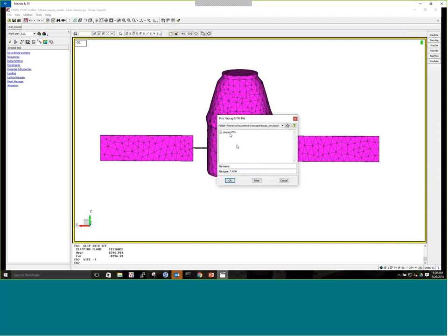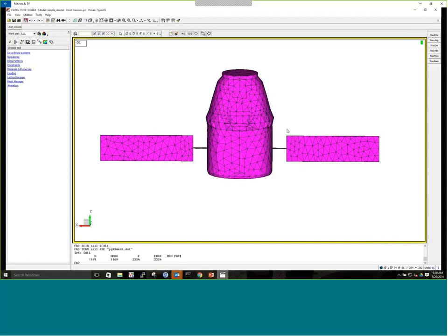What's going to happen is that the program is going to open up the object file and open up the NTM file and produce a database for Cadfix called an FRM file that contains the results information that will be loaded into this model once we've created it.